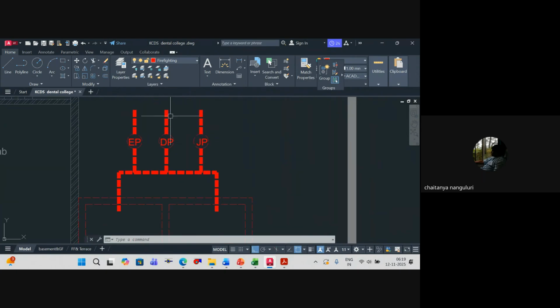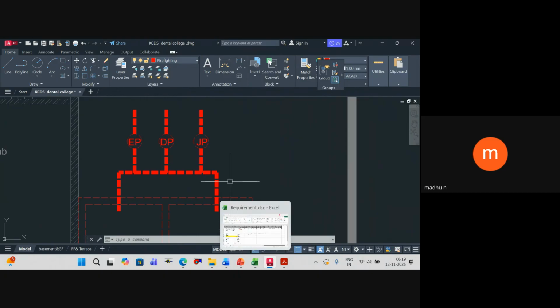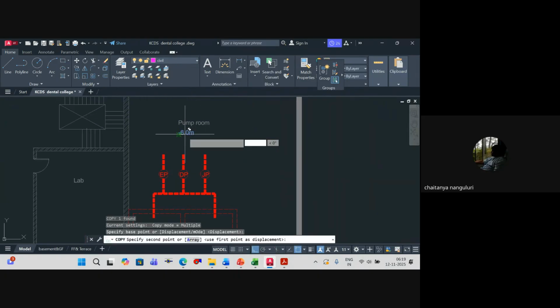So at any point of time, how many pumps will be running? One pump. So what is the flow rate? 2280. So my entire suction manifold can be designed for 2280 LPM. But in the worst case, the electrical pump and the jockey pump can run simultaneously for a very short duration. So for safety, we can take that value: 2280 plus 180 LPM.